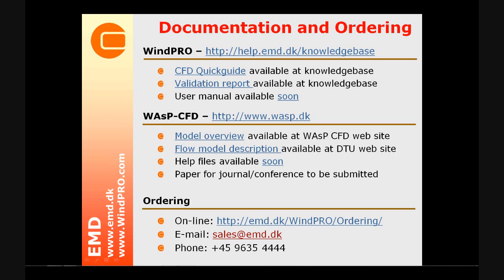And so the related question here is that, well, if profile fit has not improved, does it mean that it's even more important now to measure at hub height? Well, a comment to that is that in our setup, we deliberately used only default stability settings. And what I also mentioned, perhaps just briefly, is that we can actually improve the profile fit if we had adjusted the stability settings. And that's a post-processing. That's not something that you do before you do the actual calculation on the CFD cluster.